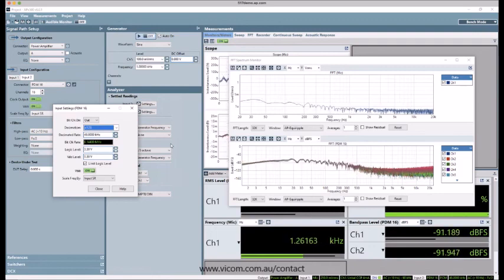But the way we get audio back out of a PDM signal is actually very simple. All the noise is above 20 kilohertz. So we just have to low pass filter and sample rate convert the signal. We'll take a 3 megahertz signal, low pass filter it, that is, remove all the energy above our frequency range of interest, 20 kilohertz, and then we sample rate convert the 3 megahertz to, say, 48 kilohertz. That's how we get back to an audio signal.